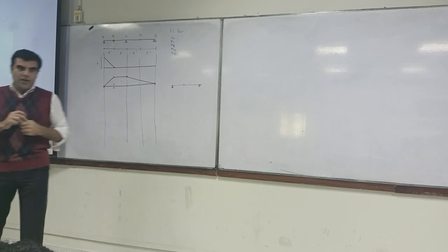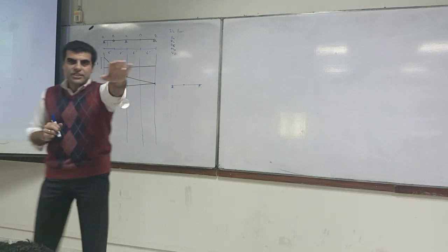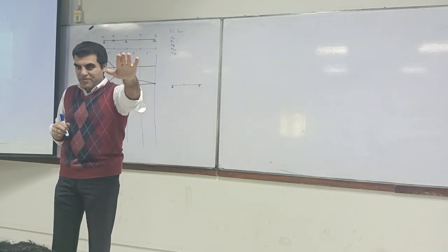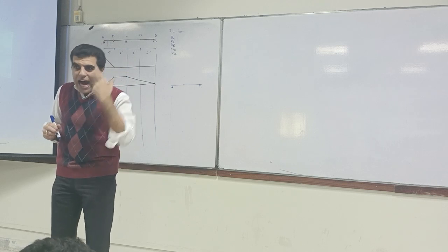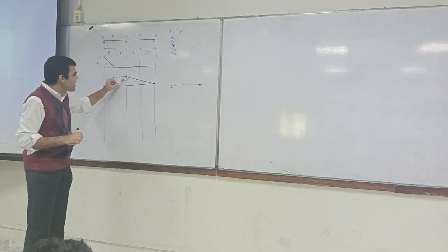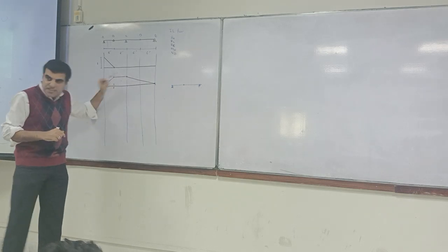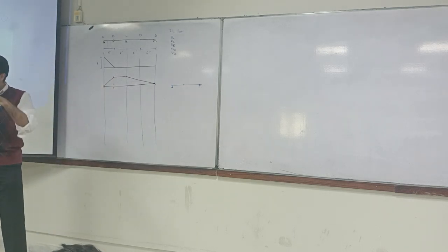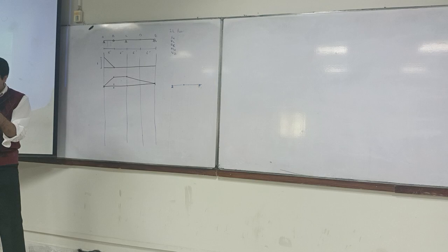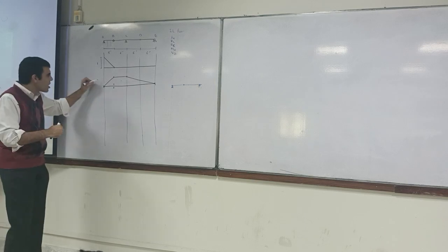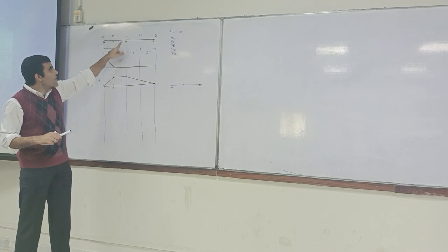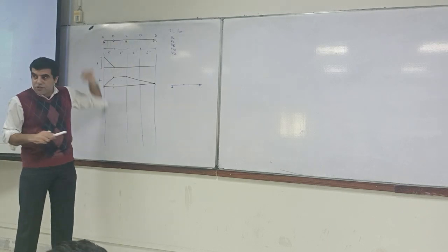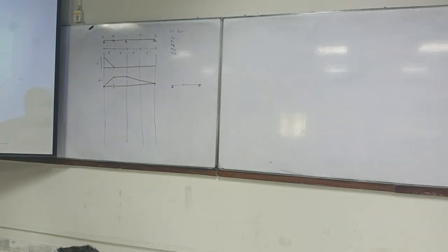Look, guys, that gentleman pointed out very rightly. He gave you the hint, and you are still saying that it is correct. How can this be correct? Why are we having a rotation over here? Is this a pin which can allow rotation? This is an external support. I told you that this is a knife edge. So this is wrong. We have removed this, but we are not introducing any pin over there. This is a straight member.